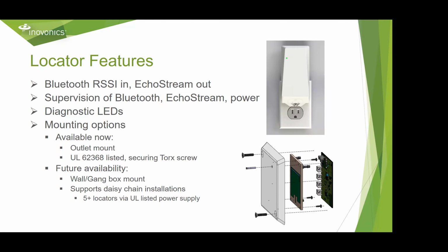You can screw it in the US. And for those of you in Canada, not sure if we can do that or not. There's a little bit of a debate on that. Technically, it might not be code, because in Canada, if there's a fire at an outlet, you're supposed to be able to kick the thing out of the outlet. Whereas in the States, we want you to go to the breaker box. That plastic, I think it could probably still be kicked out. That's never going to happen. This is such a low current draw device, and the line power is via transformer down to very low voltage. You can even put a clear plastic thermostat cover over the outlet.